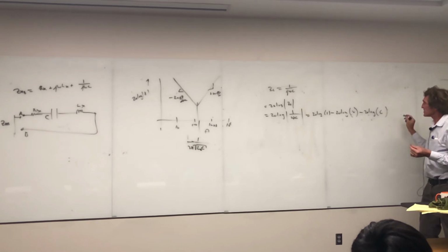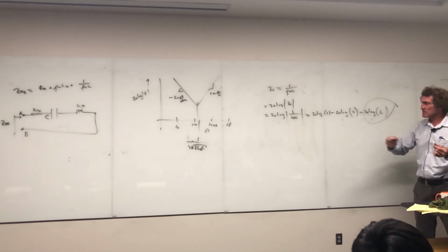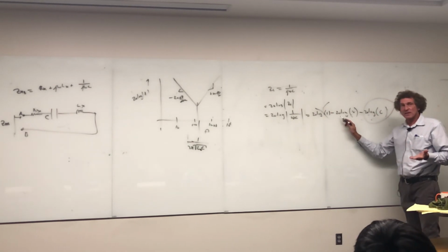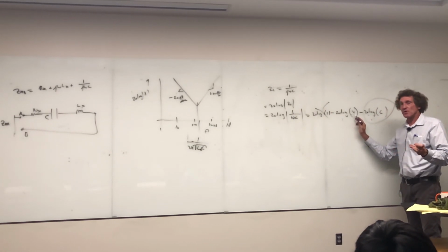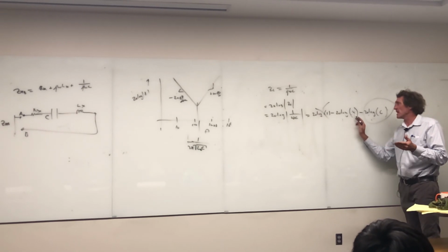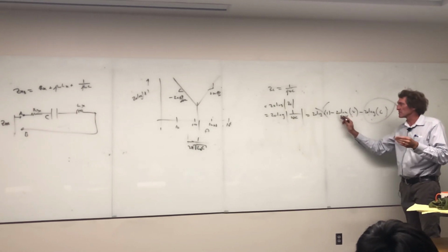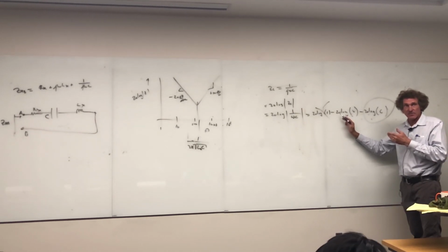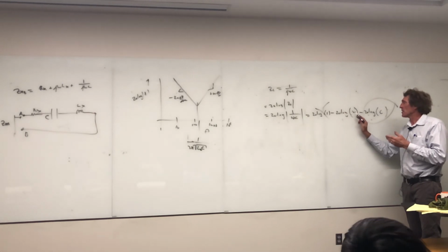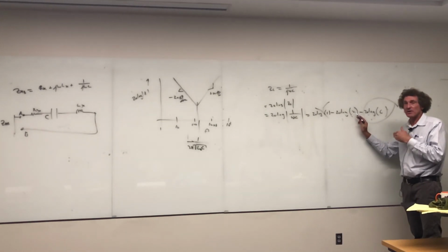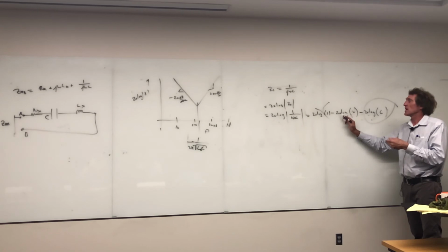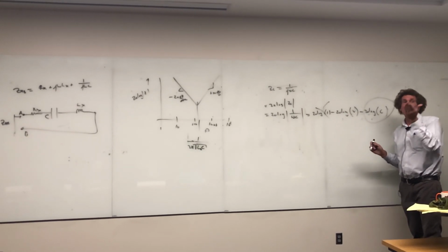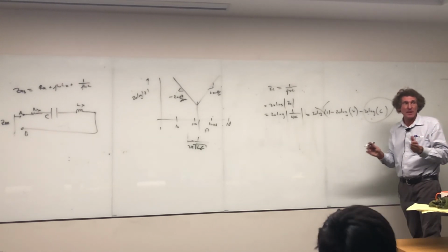Now, this is a constant. Do you all agree with that? What's the log of 1? 0. It goes away. So when you look at this, every time you go up an order of magnitude, start with omega equals 10. Well, log of 10 is 1, it's minus 20, right? Now I go up a decade. A decade is a factor of 10, correct, class? I go from 10 to 100. Log of 100 is 2, correct? 2 times minus 20 is minus 40. It went from minus 20 to minus 40, which is 20 dB per decade.